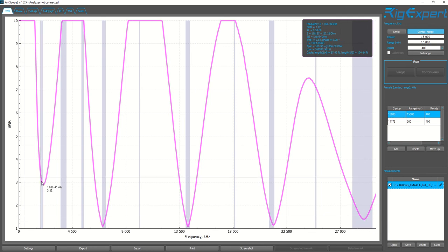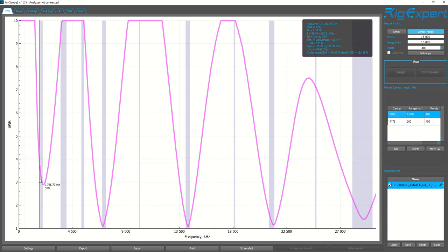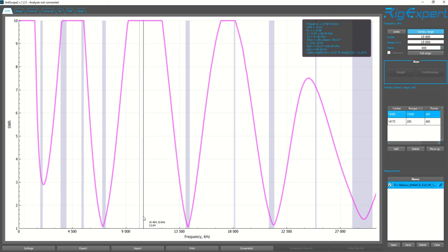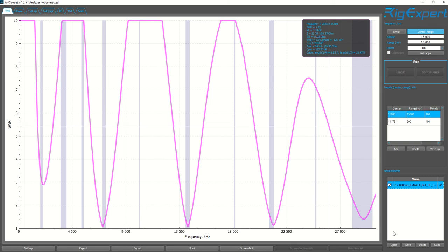With a tuner, I could even do 160 meters with this antenna. So I'm getting 4 bands, no tuner required, and it's handheld, a very small antenna. I want to compare this to my PAR end-fed, the 10, 20, 40 trail-friendly end-fed. So I'm going to open that up.